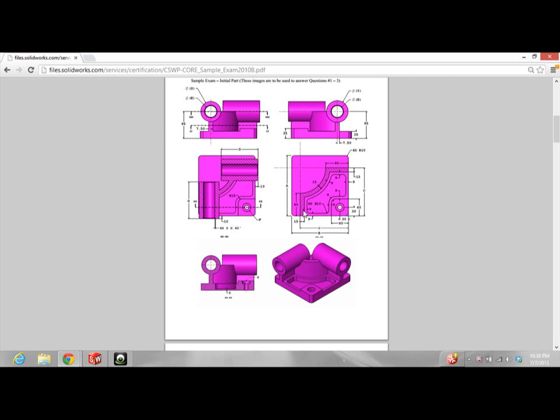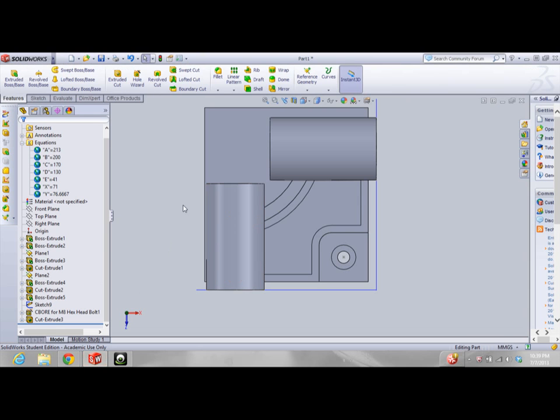So, you gotta go ahead and do the fillets. So this outside four corners is radius 10. And then we have also radius 10 on these 6 edges. And then we have these chamfers. Okay, so let's go ahead and do the fillets.